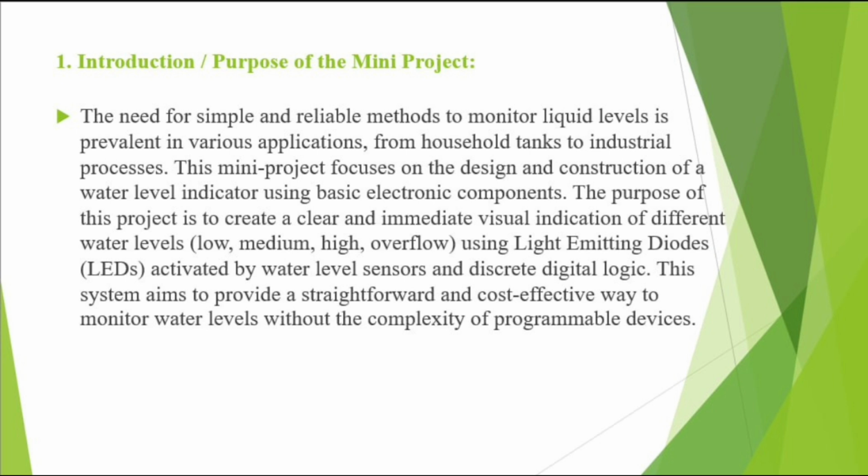The purpose is to create a clear and immediate visual indication of different water levels, low, medium, high, and overflow, using light emitting diodes (LED) activated by water level sensors and discrete digital logic. This system aims to provide a straightforward and cost-effective way to monitor water level without the complexity of programmable devices.